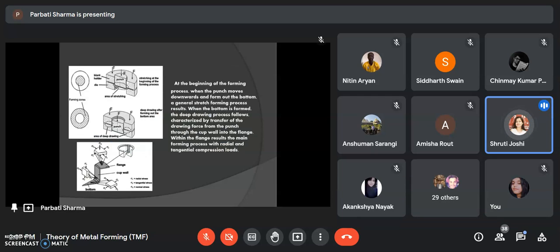Thank you, Amisha. Good afternoon, everyone. In the deep drawing process, the maximum deep drawn ratios as well as the spring back behavior of the metal parts depend on the stress distribution in the part material during the forming process. When the load limits are exceeded, failure in the material occurs, which can be avoided by additional force transmission activated in the deep drawing process before the forming limit of the material is achieved.